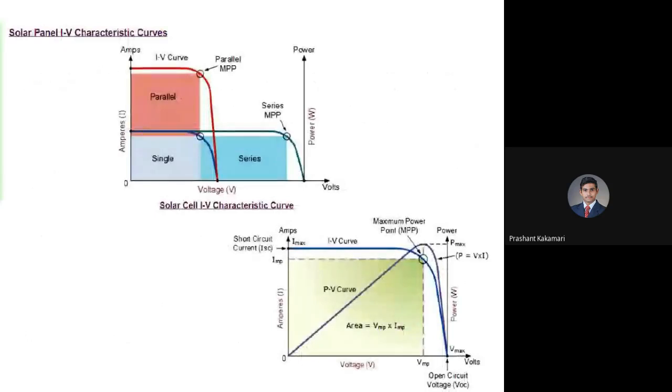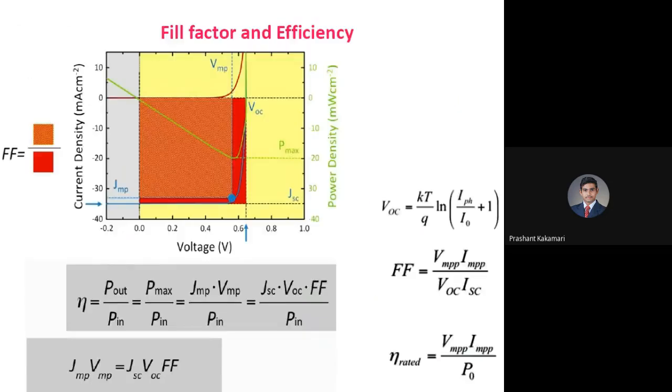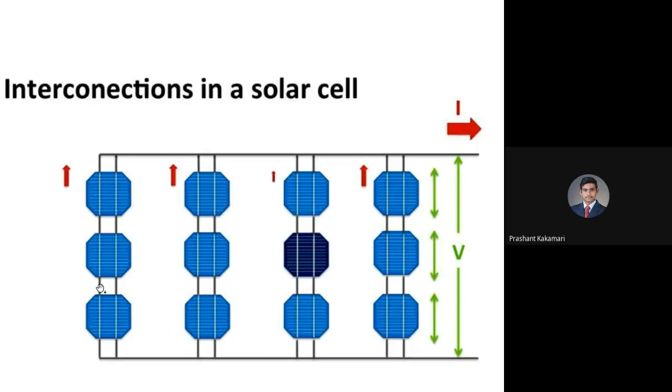The voltage between the points can be higher if you connect in series, or if you connect the modules in parallel, or you can see this sketch for easy understanding. Here, series connection of the solar cells. With the module itself, we are going to connect the solar cells in series. This will increase the voltage. And if you connect these solar cells or the modules in parallel, taking these 2 points at the end and connecting parallelly with all the solar cells or all the modules, what I'm doing is I'm going to change the current.